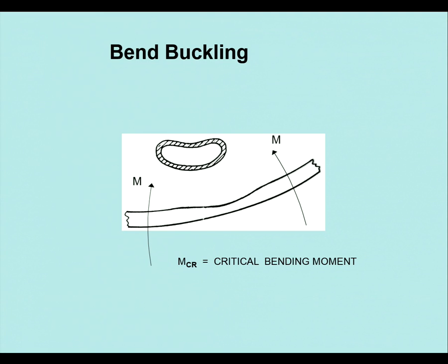So these are longitudinal stresses, sigma L. So therefore at the top it's tensile, and at the bottom compressive, negative. So we're always going to have two values for that bend stress, a compressive and a tensile. Okay?